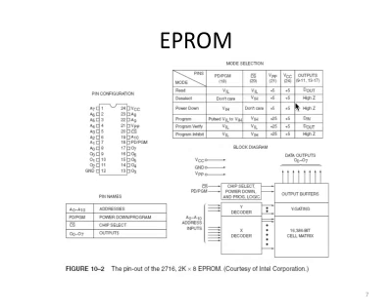After the initial programming phase, the information that you write is going to be retained in this chip, and you can take this chip and put it into your system for normal operation. This chip is typically used for BIOS, for firmware that you don't expect to change often.